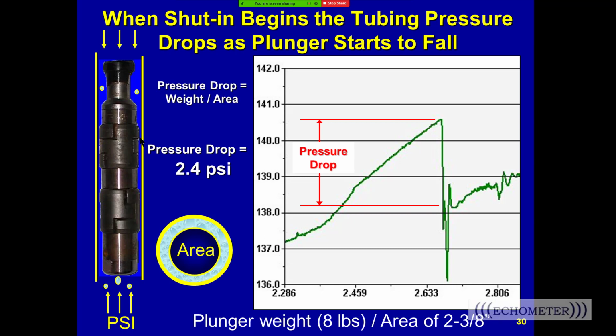I've seen wells out in Durango with casing pressures as low as 50 psi, and those are deeper than that. So I'd expect you could probably run down to 24 psi surface casing pressure, 25 psi gauge pressure on a plungerless well, and get the plunger to run and possibly produce 15 barrels a day.